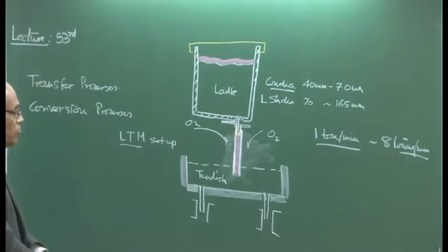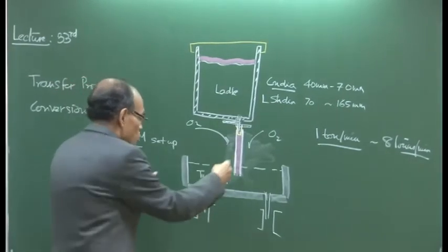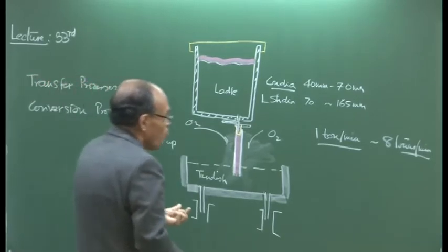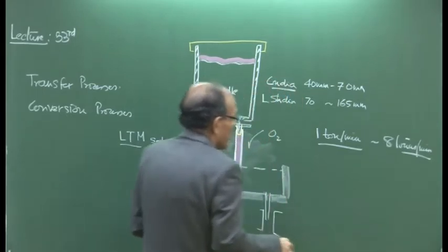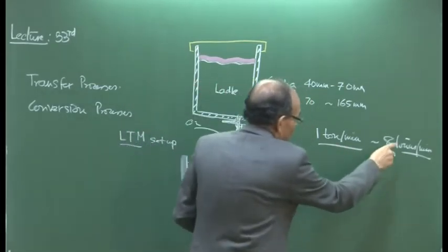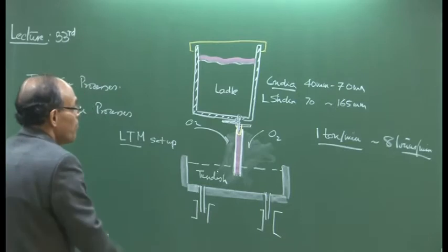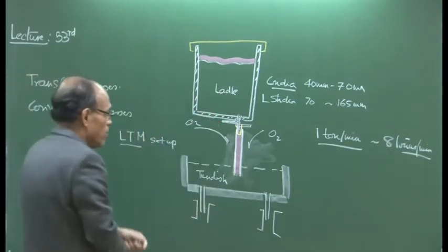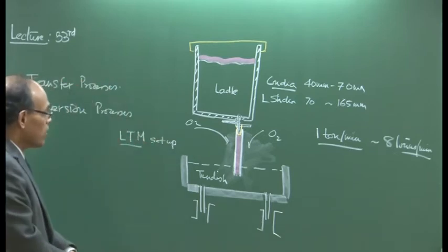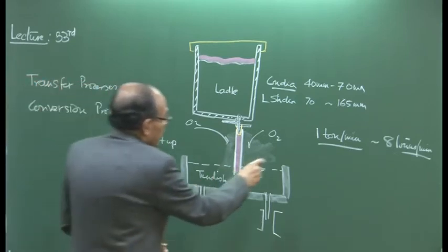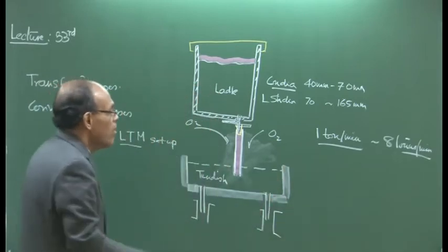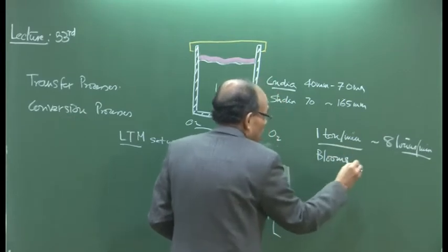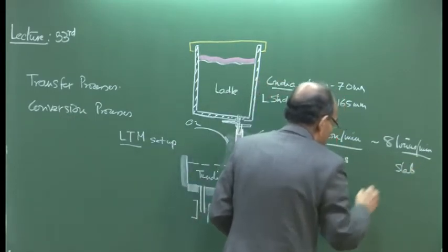So, if we have 2 slab casting molds, or 1 thin slab casting mold, in that case the casting rate or the throughput rate could be 8 tons per minute under steady state condition. I will tell you later on what that steady state condition implies, and in smaller section castings which we call bloom casting. So, blooms, again I will distinguish these products, and this is possibly for slab casting.